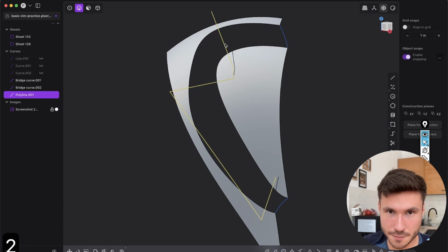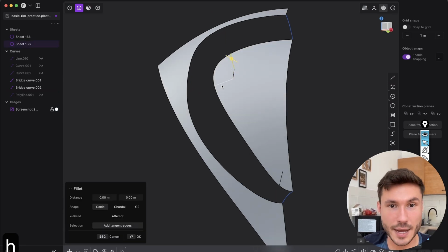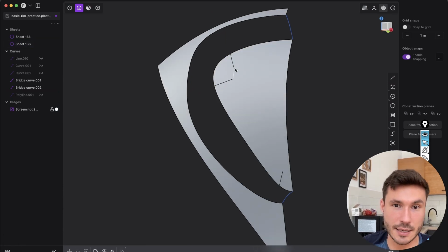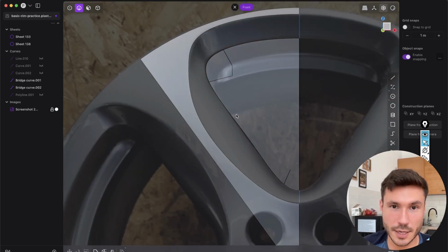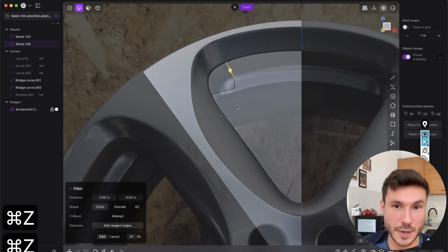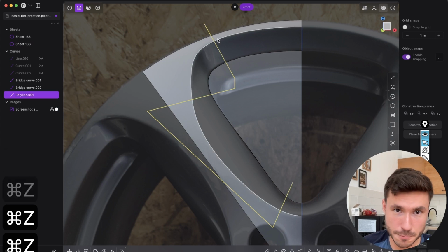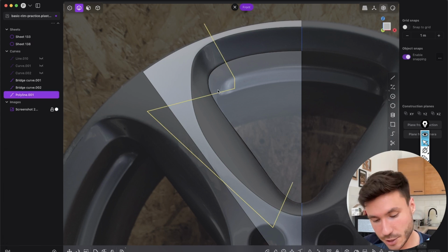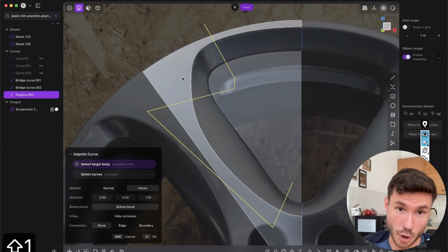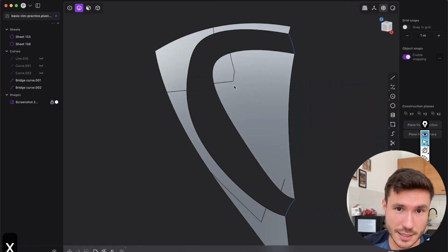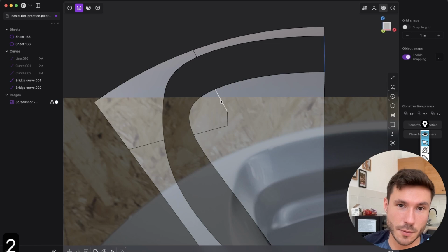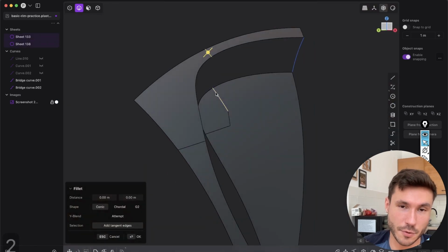And you see, if I hide this curve right now, we have some extra edges. It doesn't look beautiful, but it has to work, right? And we have to do the same here. So select this curve again, and again, Shift 1 or imprint command onto that outside. Okay. And now you don't need that anymore. And look what we have. We always have some beautiful edges here.